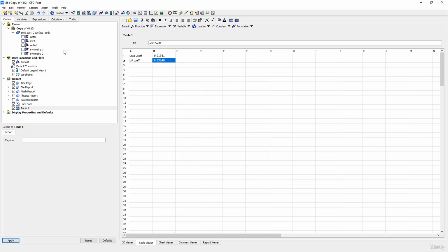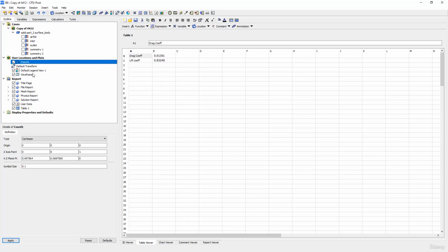But the benefit here is that if you change anything in the geometry, in the meshing or in the Fluent part, like you can change the Reynolds number by changing the velocity, density, or viscosity, or you can change the angle of attack, these expressions will be same. But just for the angle of attack, you have to put that angle of attack coordinates for the x, cos alpha for the x here and sine alpha here.